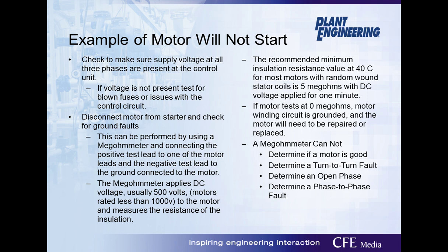Here we're looking at an example of a 460 volt AC induction motor that will not start. Once we go through the preliminary test that we covered earlier on testing for supply voltage at all three phases and eliminating any blown fuses, we move to the next system component. The control circuit is tested to make sure proper supply voltage is coming out of the unit. If a fault is coming from the VFD or soft starter, use the codes given to help troubleshoot the problem.